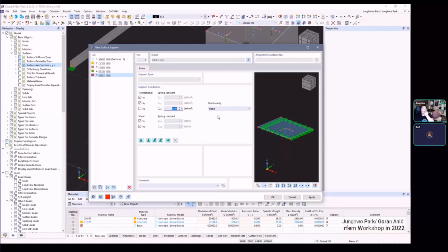If it's for example rock on the ground and very good for foundation, this value can be also 50,000 or 45,000 or 60,000. It can be greater, it can be lower, but I'm just giving some example. So I will take here 15,000 for a spring, and what can I see?